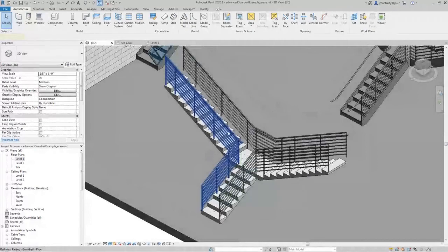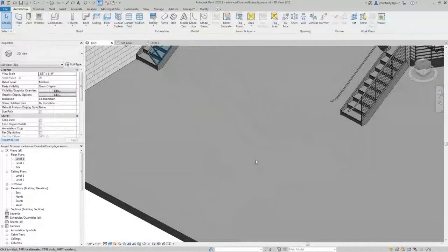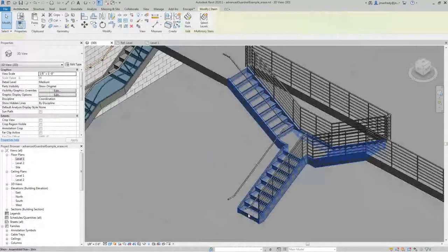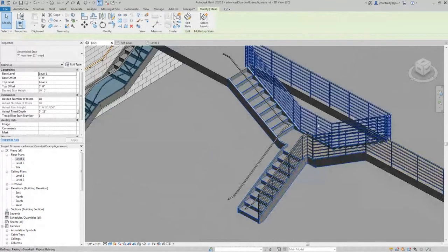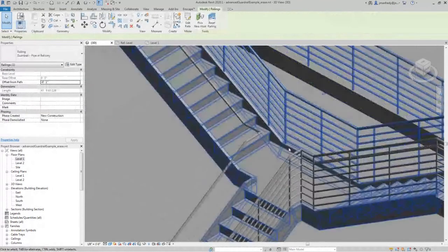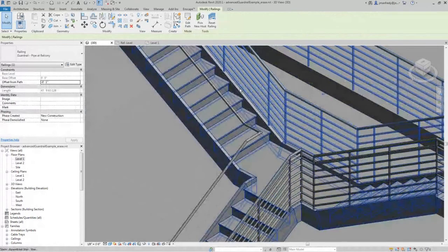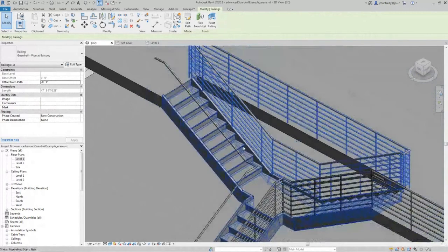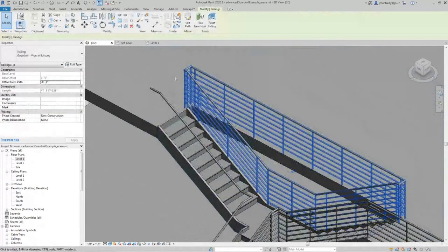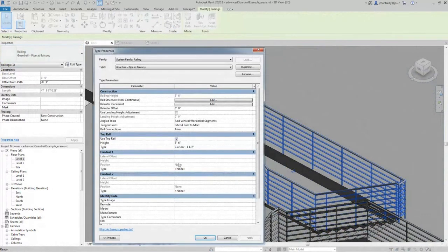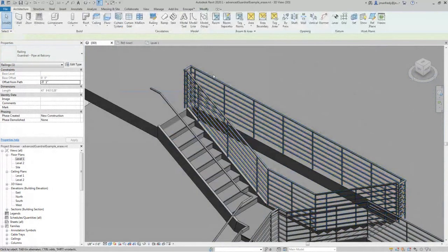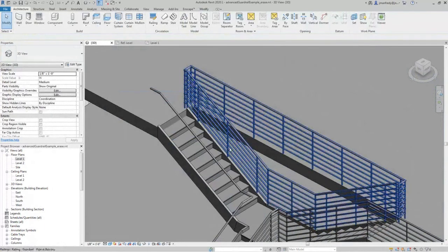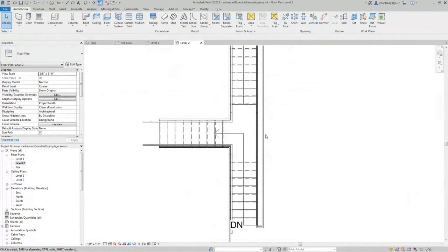So that's some of the strategies you want to take into effect. So delete this, delete this, delete this. So that's what this is. A stair with this mirror to the other side. I drew this railing here. I decided where to subdivide these railings so they're in the center of these steps. I deleted the handrail from this design. I called it pipe at balcony. And you'll see here, there is no handrail. It's just a guardrail, so I don't fall over the edge here. And I wanted to wrap up and around. So I literally, on the second floor, you'll literally draw that.